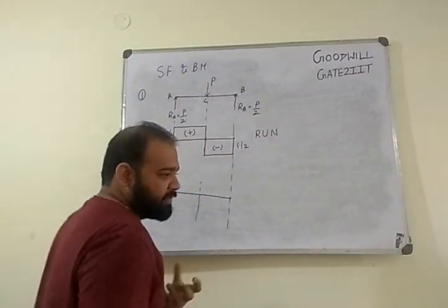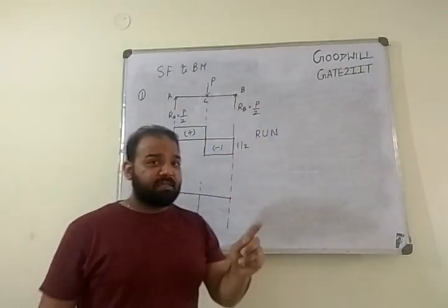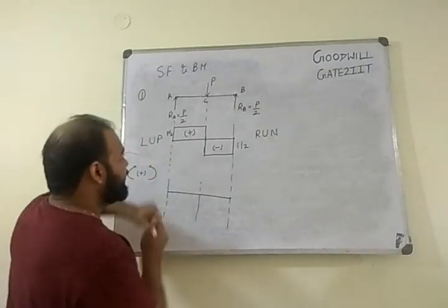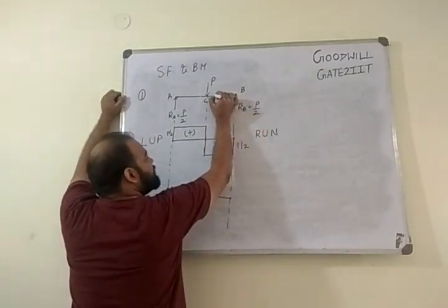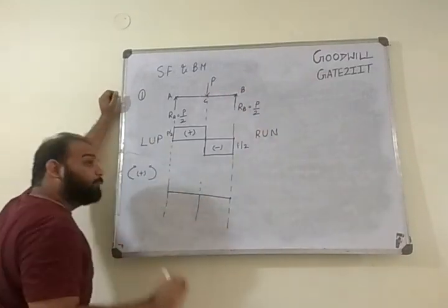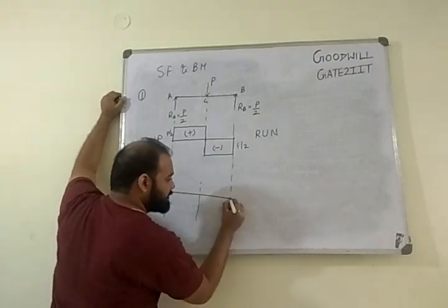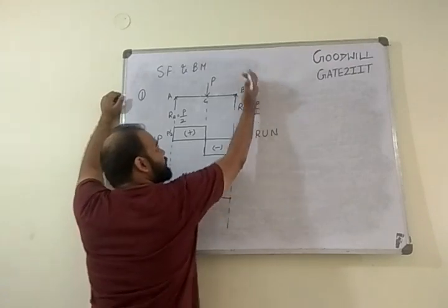So what I'm trying to say is, the bending moment diagram for a point load is linear. That means you're multiplying it with some distance. Correct, right? So 0, increasing, increasing, and you will reach C. After that I have doubt, I'll stop. How is this load increasing? It is increasing linearly. So I'll start from 0, and is this positive or negative?